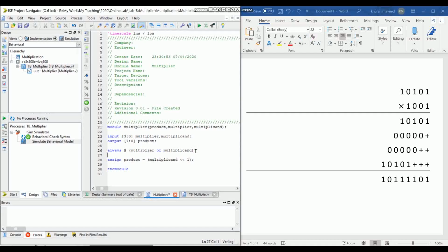So now let's write begin, which means that we want to begin this block, and here we specify the end. Right. So whenever we are implementing any logical circuit using behavioral modeling or this always block, we specify this output as reg type.